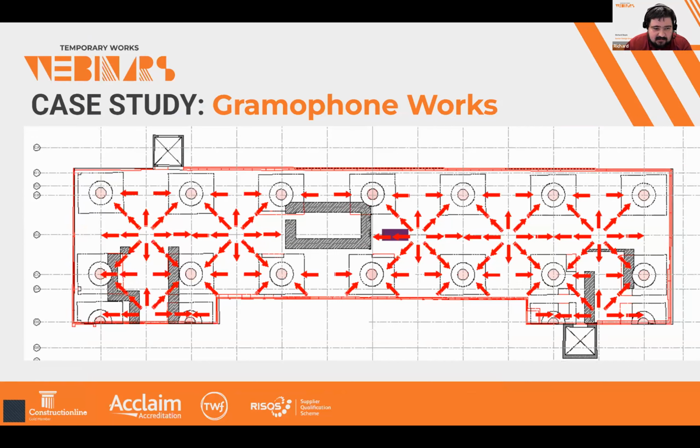So when you have all these columns holding up these floors, you get a very organized and neat and tidy load path going through the structure. Keen-eyed people will notice I've left out the one in the middle by accident, but that was a slab at the time, and the hole was put in afterwards. But this load path is very organized, very typical. But to make these large holes, you'll see that you interrupt a lot of these lines. So on the left, you're interrupting lines going towards the columns at the bottom, and some bits of slab are left floating in certain locations, which all this had to be considered.